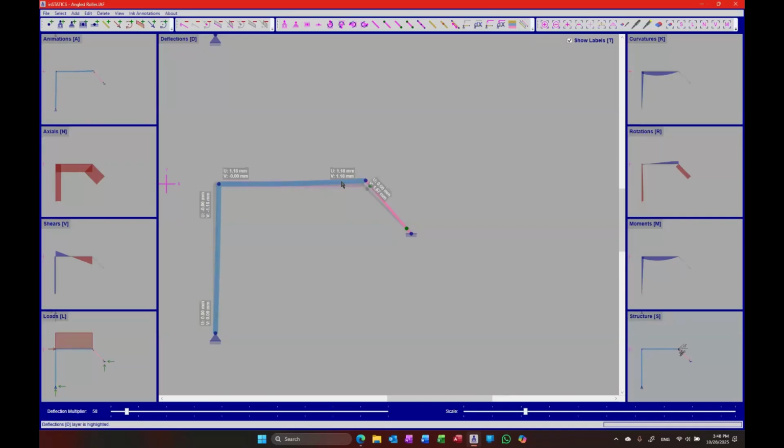Because this is a 45 degree. Now these two are identical, and they will always be identical because it never gets shorter. All of the movement happens on a theoretical line, right, that goes across like this, at a 45 degree angle. So I simulated a 45 degree roller by just adding a theoretical element into my model.